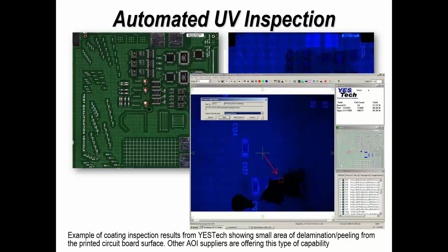Again, that takes time, so don't underestimate the time required to set up a program. Just like with AOI, SPI, any other automated inspection technique, you need time to set them up and get them right. But when they're right, you'll only get rejects highlighted that are real rejects rather than the ones that are not really rejects that people skip. So again, that's something else to consider, particularly if you're working for high-end products within the marketplace.